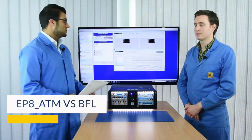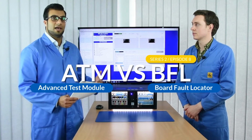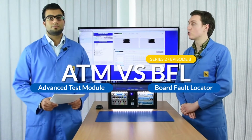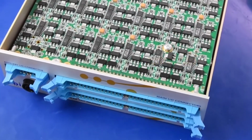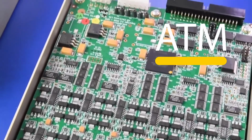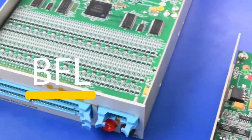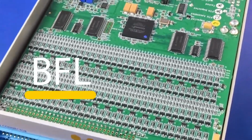Exactly. Okay, so in episode 8, the previous episode, we looked at the differences between the BFL and the ATM and how these two modules work hand in hand. So Oliver, what can you tell us about these two modules? So in the last episode, in conclusion, we found that the ATM was best for those system-wide PCB tests, and then from there we'd find the routes and the areas where we might have suspicions, and then we'll go in with the BFL to test those components. And that's how our customers used it in their test rigs. Our military customer had that bed of nails, and then we had our energy harvesting customer who did the exact same thing.